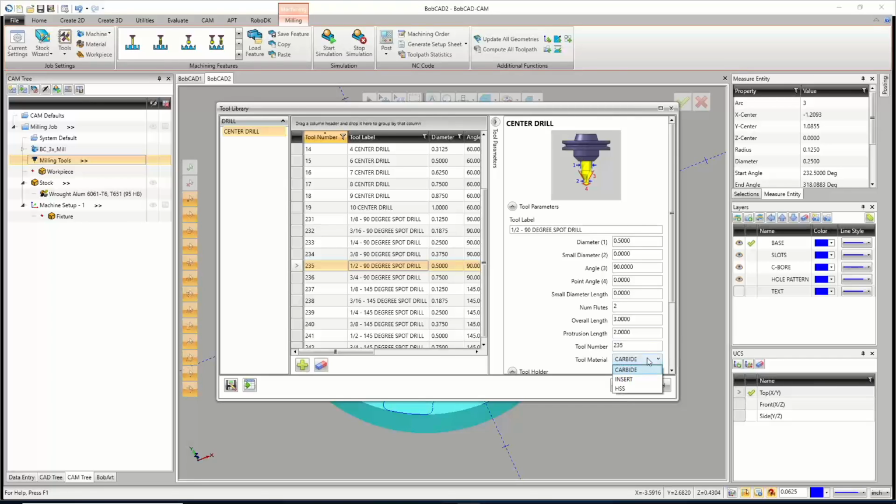You need to make sure that that's set up correctly. If you're not doing that part, your feeds and speeds are going to be wrong anyway. This is to help get you as close as it can, because it knows the feed per tooth and all that stuff. It calculates it correctly, but it might not be the exact values for your tool.